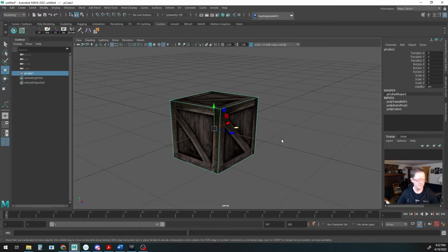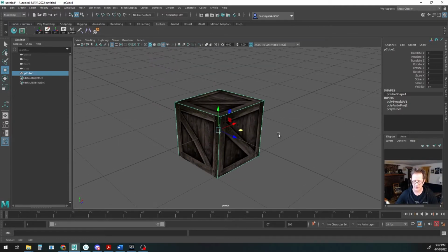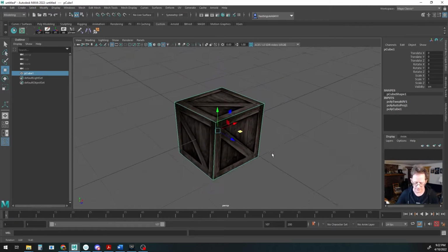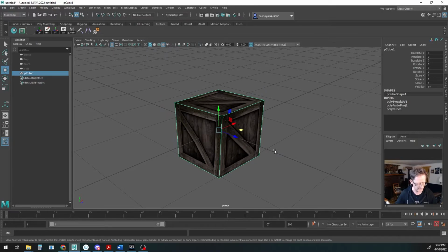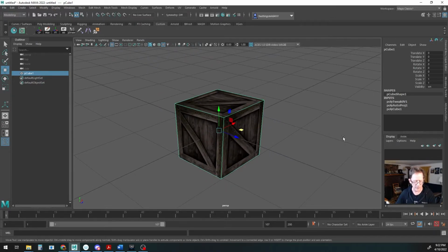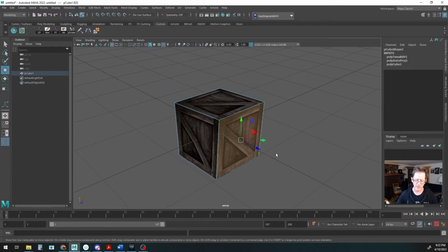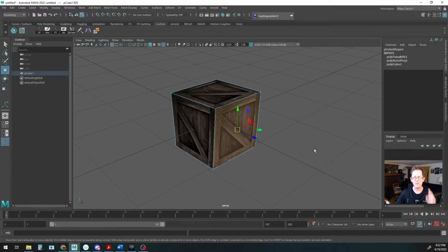What I want to show you just before we finish this is what it's like when we add faces to this. So let's press F11 and go into face mode. We'll click on one of these faces, and then we'll do two commands that will make new faces. One is the extrusion, and we can extrude a face. You can extrude also an edge, but you cannot extrude a vert.